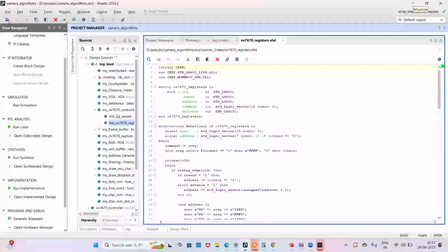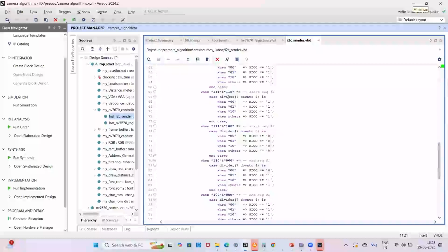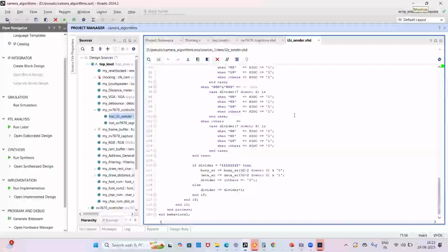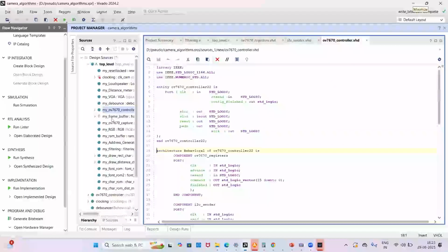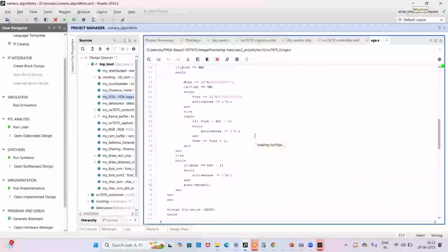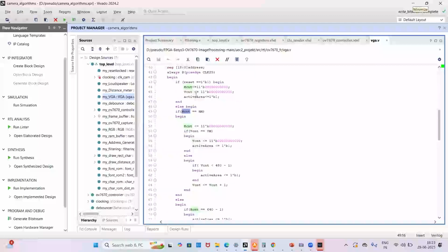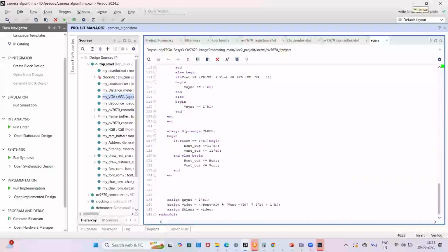So this is how my register settings are happening on my OV7670 camera, and the FSMs are working on certain output frequencies. Yes, so the I2C setting controller is completed on that. Now the VGA output is how I'm determining the resolution for my VGA count. As you can see, my vertical counting and horizontal counting is completed. Only then my active area is enabled, and when my active area is enabled, I'm sending my video on this output format.